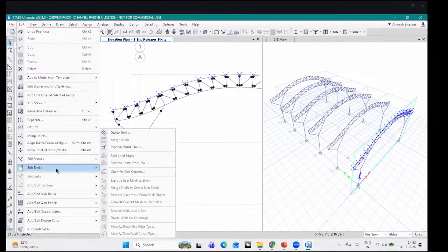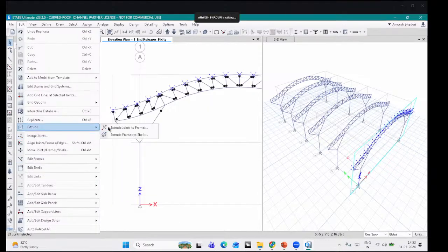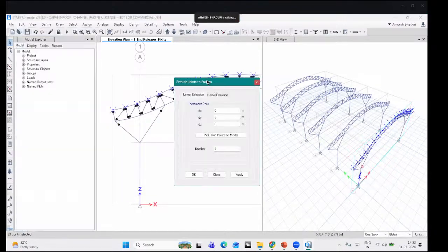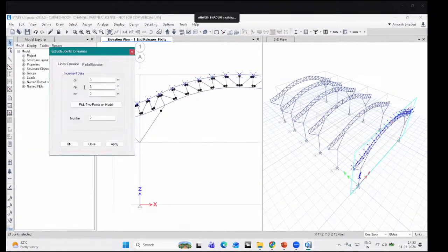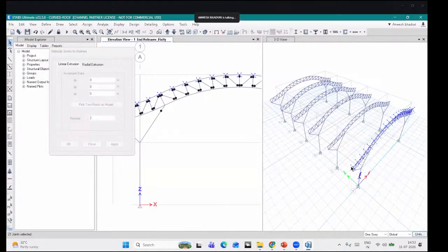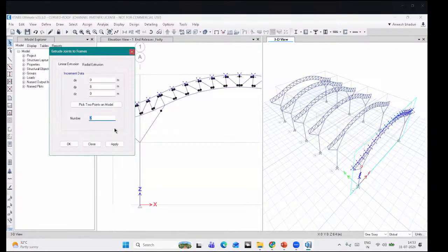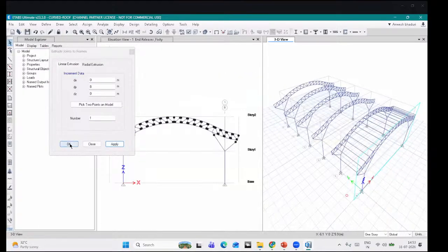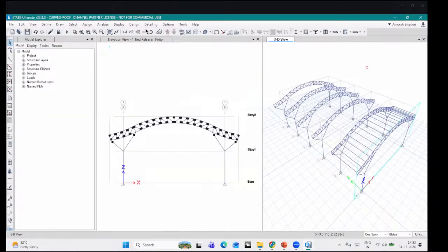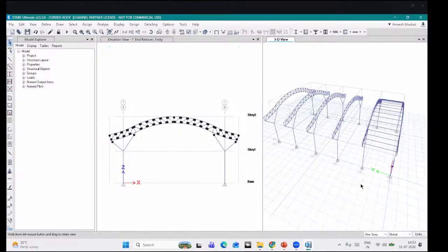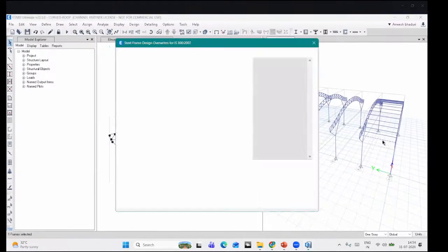So for the branch columns, in the extruded view, you can see the member properties have been assigned, that is 76.1, 3.5. Now we will be sorting columns. Some of these members, since they have a very small inclination to the vertical on import, vertical grade, they have been assigned as column properties. Turn on the elevation 1.